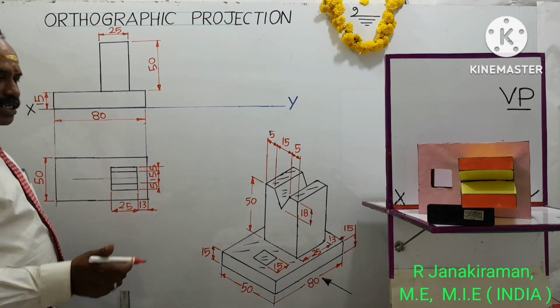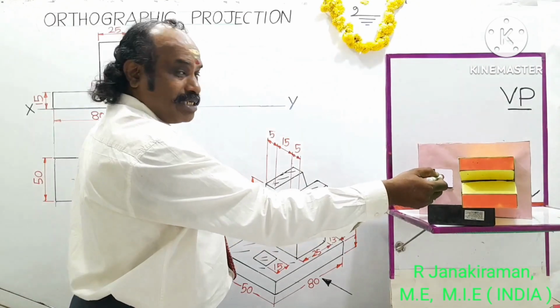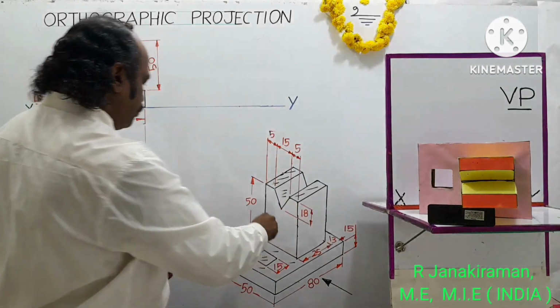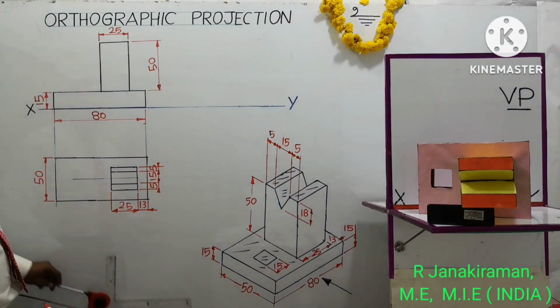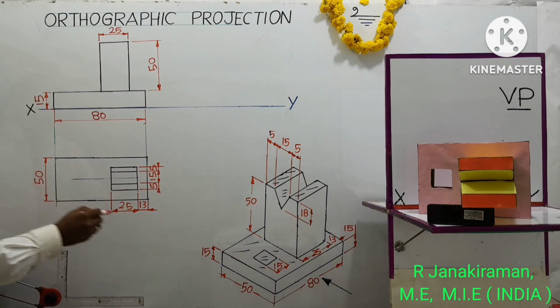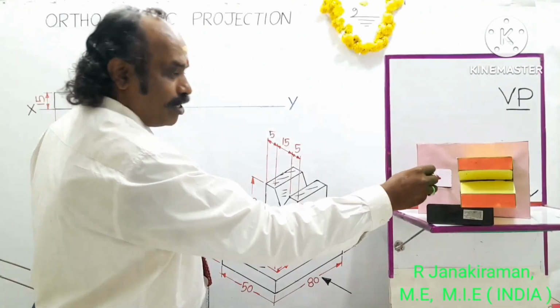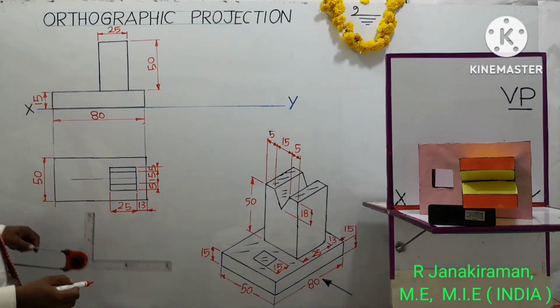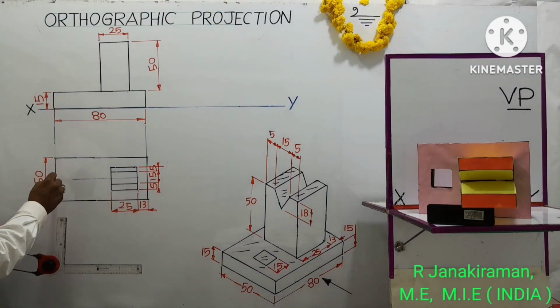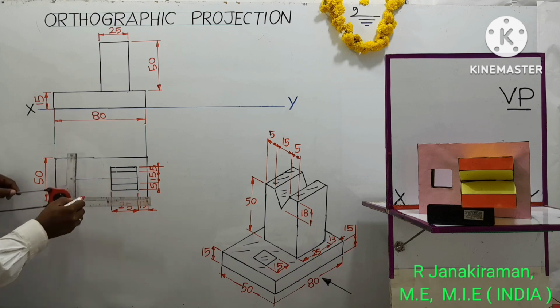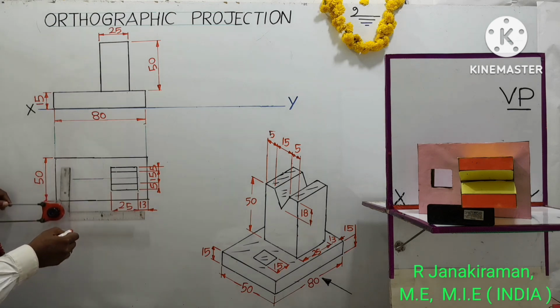Okay. So next, another square hollow is there on the base part of the object seen in the top view, of side 25 mm. So measure this. It is on the center of this part, the center of the remaining portion. The square hole size is 15 mm. So measure this horizontal distance. Whatever distance is there, at the center you locate one point.